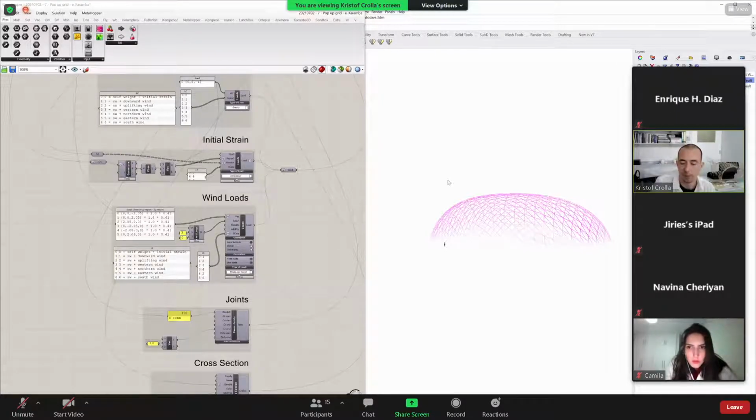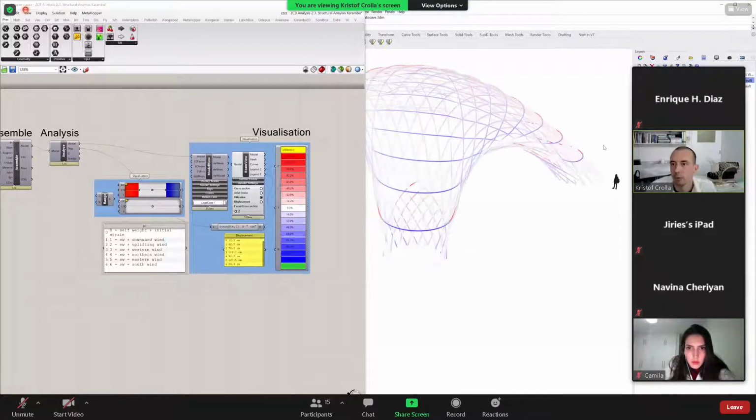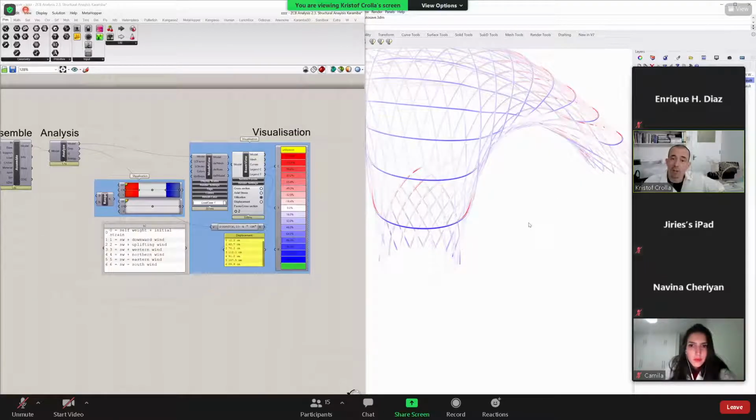What you would change there, as I mentioned earlier, is maybe going for thinner diameters, or going for splits, or going for bundles. Because from the calculations that we have visualized here, which is very clear in the ZCB Bamboo Pavilion, for example, for all the loading scenarios, it's primarily there that the bamboo will start to fail. So this is actually an argument against working with singularities, or against changing the designs to the degree that we have with bamboo as a material. But if you can find a way to get rid of the shear forces there, then there's no problem.